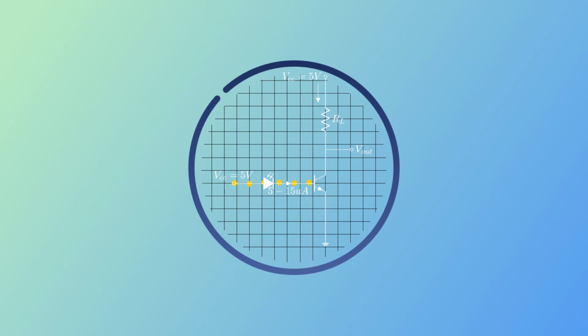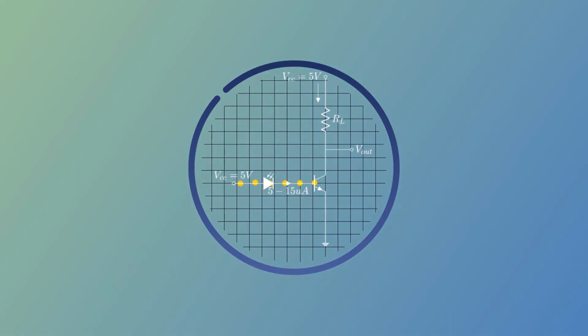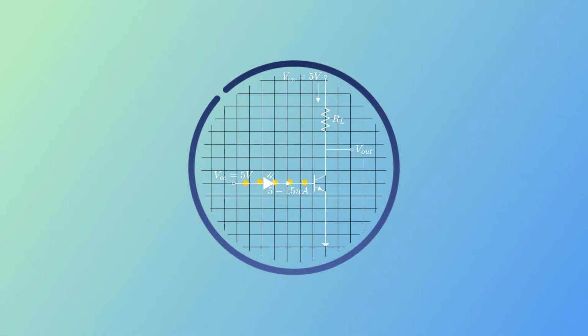Suppose that we want to detect the ambient light intensity to change the brightness of our phone. We can utilize a photodiode for this application. Since photodiode converts light into a small electric current, this small current needs to be amplified into a larger one and preferably be converted to a voltage signal. We can achieve all this by using a current amplifier like this.